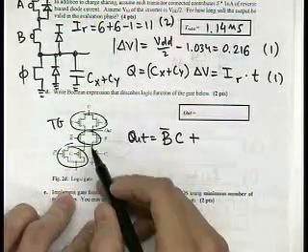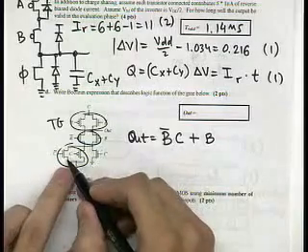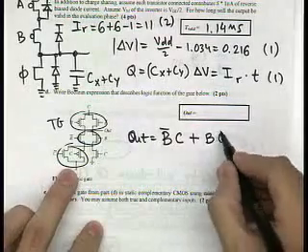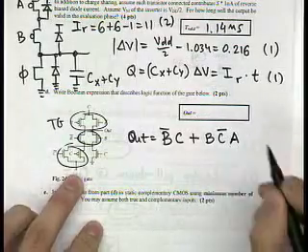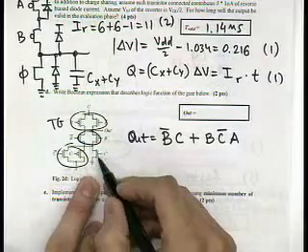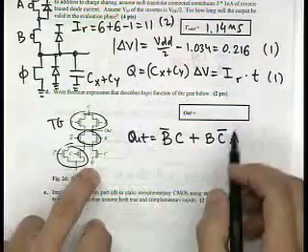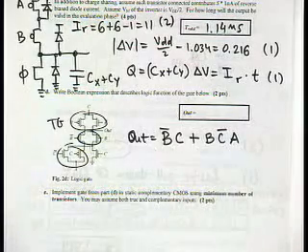Then I have another transmission gate which is B, and this transmission gate is turned on by C bar, and it picks up signal A, right? And that's enough, because now you have this pull down guy. If you start messing with this one, then you may end up with some redundant terms. Everybody clear with that?